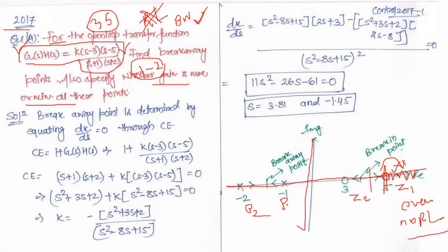If you are standing here, if you count the roots, then it comes to be 1. So it is odd, hence the root locus will lie. So root locus will lie from 5 onwards till this point. Similarly, if you are standing exactly at plus 3, still the count is odd, hence root locus will lie till plus 3. If you are standing here, let us say plus 1, then obviously the count is even, hence root locus cannot lie in this portion.